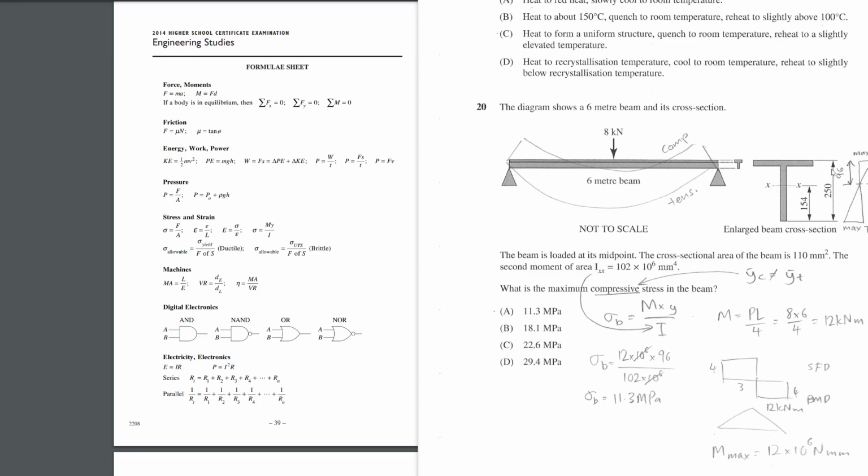Now, normally, when we find the bending stress, we want to find the critical bending stress, and that's why I have a video somewhere where I say big Y, and I'm doing like a Y shape. The problem with smartphones. But anyway, big Y. If in doubt, use the big Y. Right? We've got two Y values. We've got Y for compression and Y for tension. And these are not the same. The Y for compression is 96 and the Y for tension is 154.